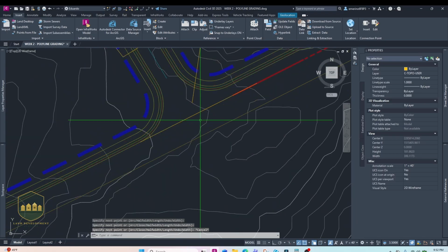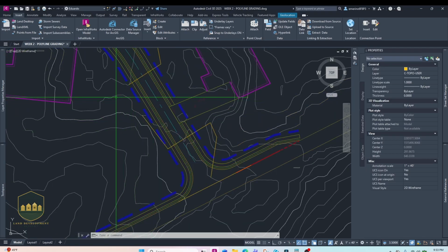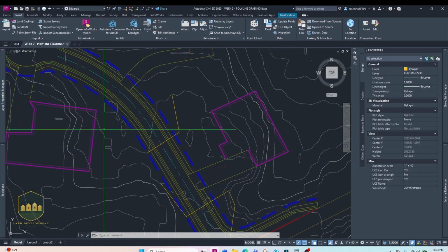Now, really what I'm telling the contour to do now is, for example, you have this 324 coming here, wrapping around, hitting the existing road. And then now I'm telling it, instead of doing all of this, go ahead and follow my contour. So boom, boom, boom, boom, and then it's going to spit back out and continue on its way right here. I'm just redirecting where this line is going. Same thing here. It's coming down, doing a little loop, and then boom, boom, and then continue on your way.